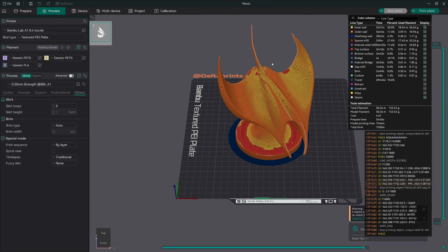I'm going to go ahead and close out this window because when I changed over to the Bambu Lab printer, some additional options under the print plate button showed up. You can now see print plate, print all, send, send all, send to multi-device, and export options. It's pretty simple to remember what these do. The print option will start your print on your devices. The send option will upload the G-code to the device and hold it for printing later.